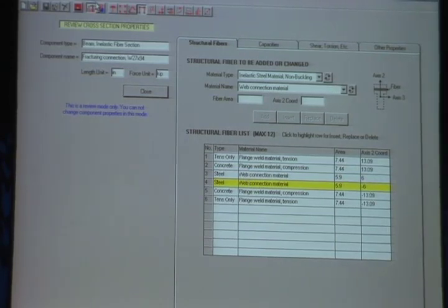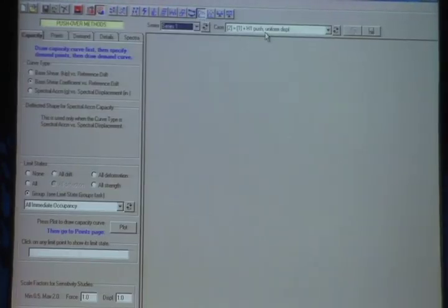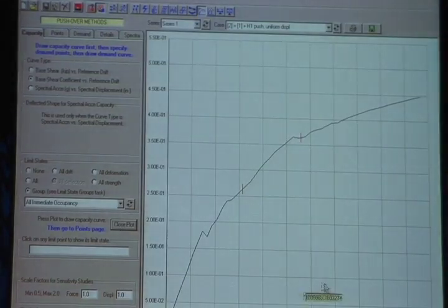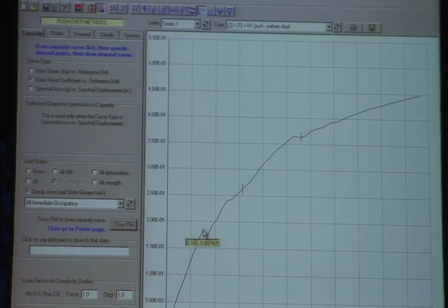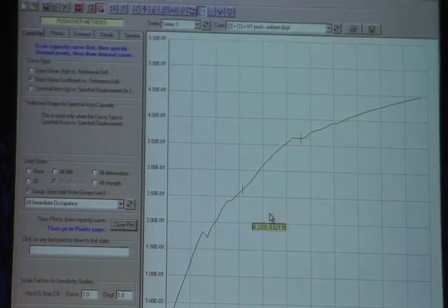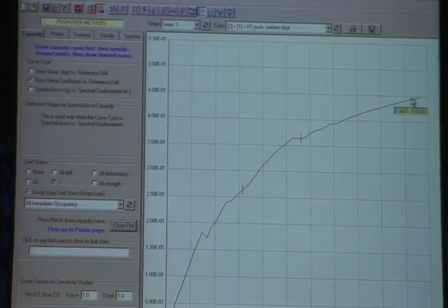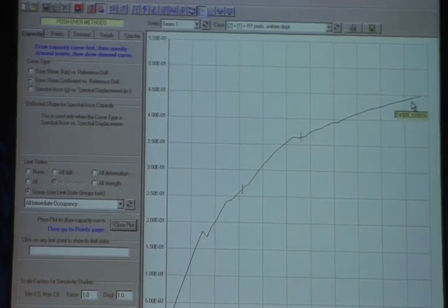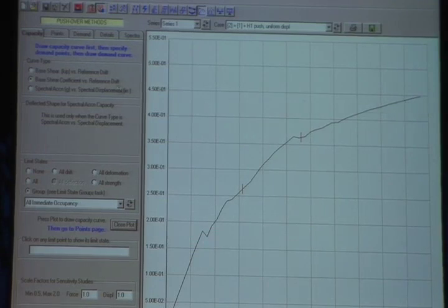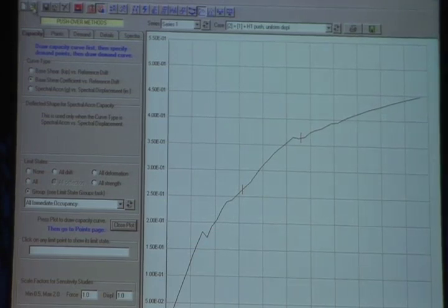And then I've run analyses, and I've run a pushover analysis in the H1 direction, and I'm going to plot the pushover curve. And there's some jiggles here. These jiggles occur where the connections fail. And without going into details, it can tell you by the time it gets out to the end there, every one of those connections has failed in tension. And remember this number, it's 0.45 G. There's a strength out here, about 5% drift. Okay, then I'm going to go to a second model.